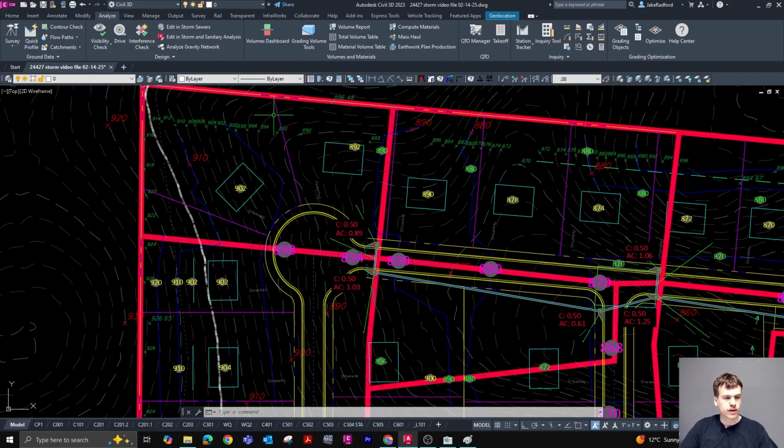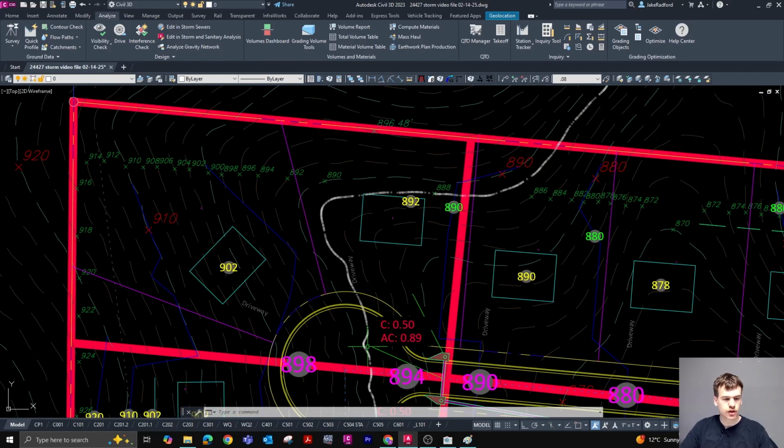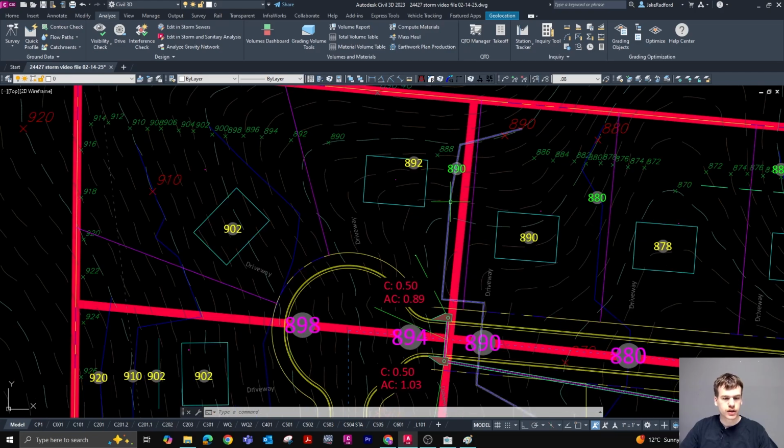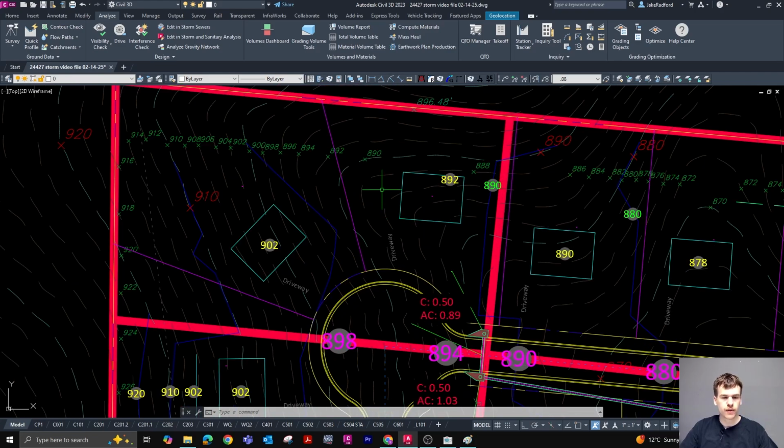So once you have your drainage areas delineated, you can look into each drainage area and estimate the runoff coefficient based off of the amount of proposed impervious in that area. It's extremely tedious and takes an extremely long time to calculate the exact amount of impervious in each individual drainage area, and then use the different types of impervious surfaces and the slopes across the impervious and pervious areas to determine a super specific runoff coefficient.